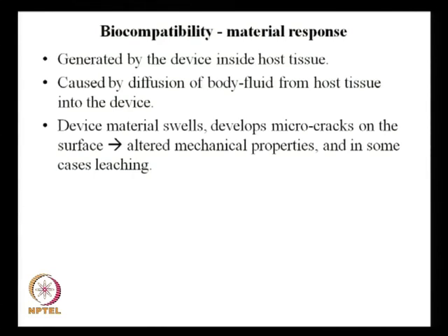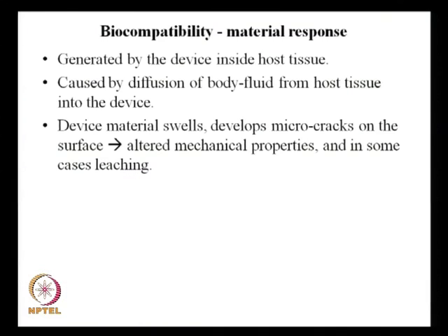Swelling involves, the moment it starts swelling, you don't know what is going to happen, because you are stretching it. Some place it is getting stretched, some place it is not. So, there would be stresses developed, and at any point there could be a crack developing. So, swelling is something which you have to be careful with. It develops micro cracks on the surface, and it can have altered mechanical properties. If something swells, it has to have some kind of structural integrity, and that integrity would be lost.